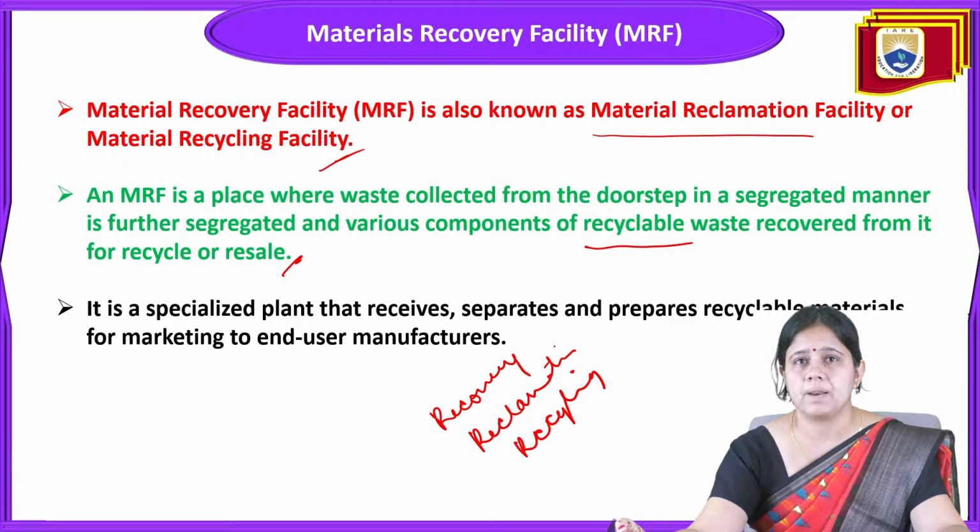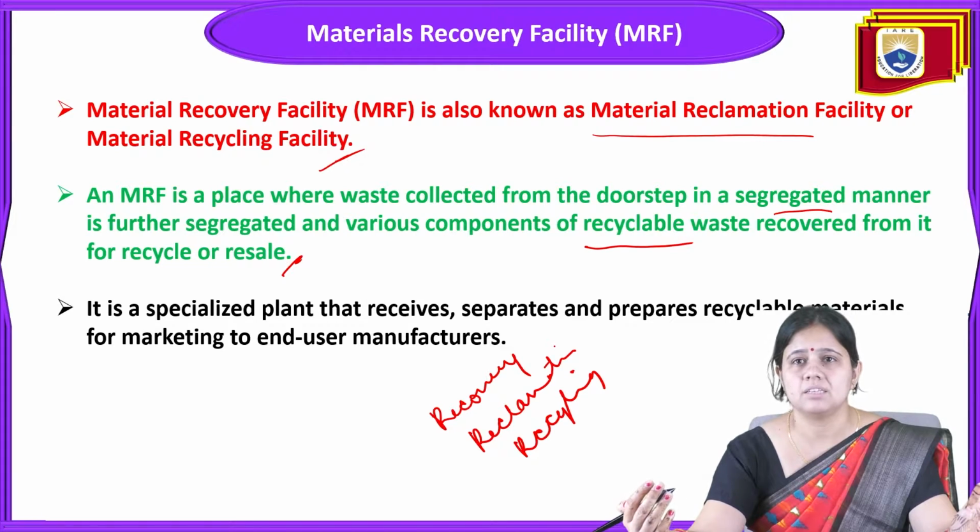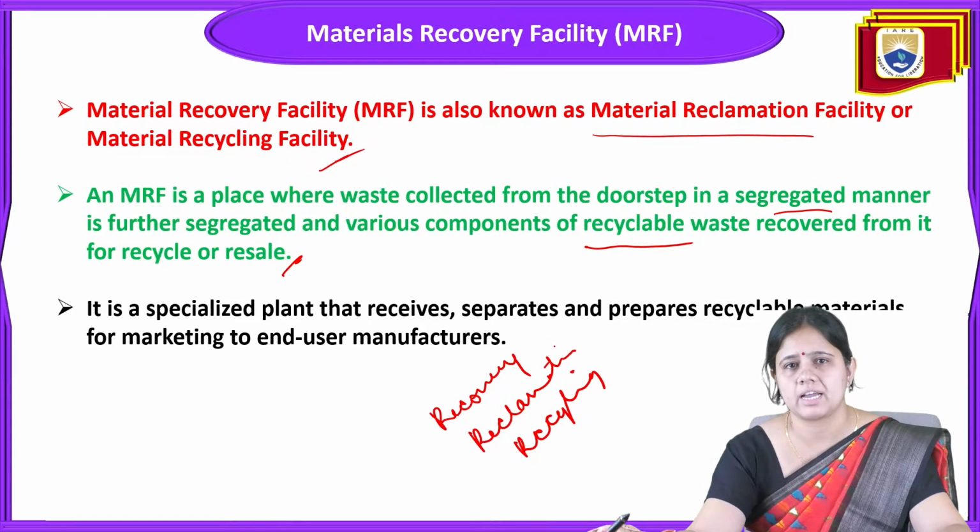MRF is a place where the solid waste is collected from the doorstep in a segregated, differentiated manner, like from the curbside. Whichever waste collection method is used, the waste is collected at the doorstep in a segregated manner, and then it is further segregated.